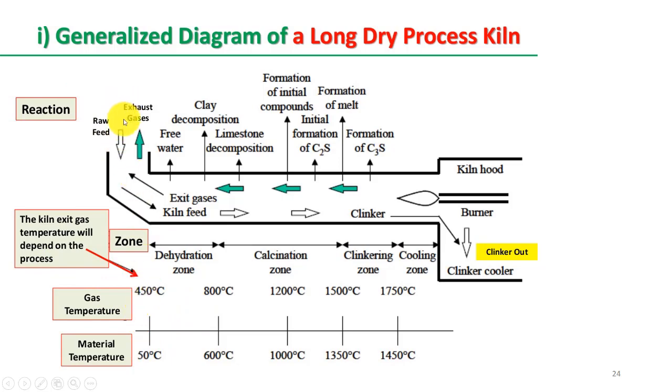And the first temperature starts that the preheating is occurred. Basically, we preheat the material so that the material can get into a reactive form, and limestone is not as reactive in raw form. When you preheat your material, the limestone is converted into quicklime, which is very amorphous, very reactive to react and get the products in a very short amount of time.